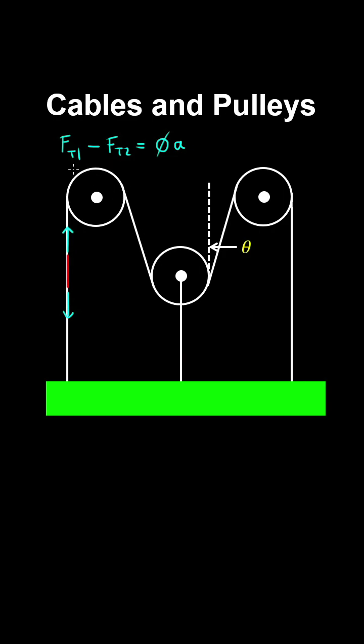So in other words, if we isolate this top pulley, then the tension force acting on it is uniform, and of course you're going to have reactions at this pin to prevent the pulley from moving. So you'll have a similar configuration on this side, and on this side you'll also have the same tensile force in the cable. So if we take a free body of this pulley here, then this force, so basically we just resolve these forces into vertical and horizontal components.